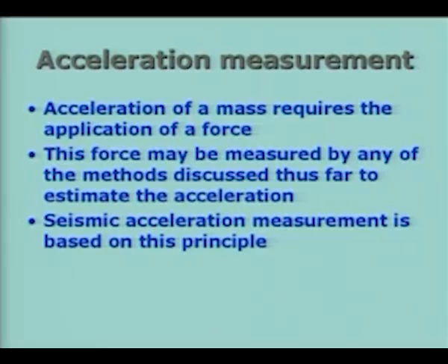For example, seismic acceleration measurement is based on this principle. We subject what is called a seismic mass to an acceleration, and this generates a force. This force is measured by a spring which is going to be displaced because of this force acting on the seismic mass. So, the measurement is actually the displacement of a spring, and that is equivalent to a force. This force is equivalent to an acceleration because it is multiplied by the mass. Knowing the mass, I can find out what the acceleration is. It is a very simple way of doing it.